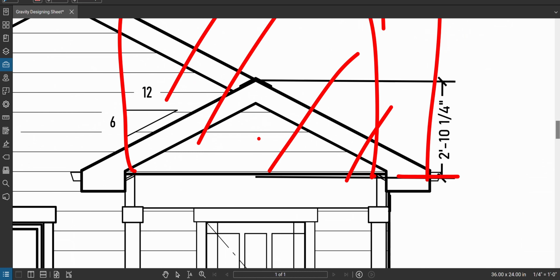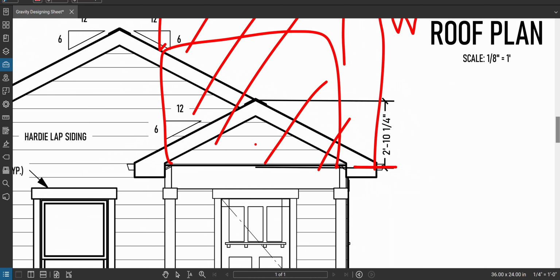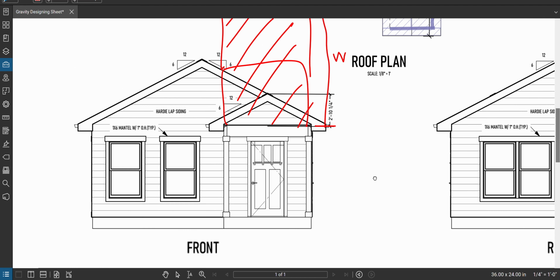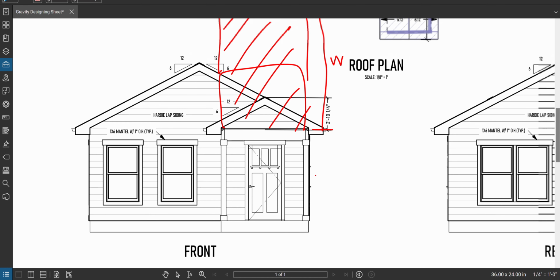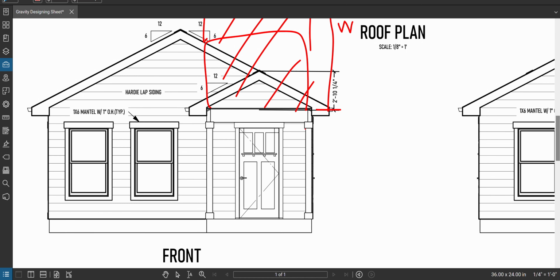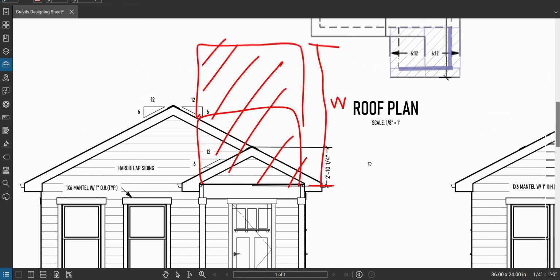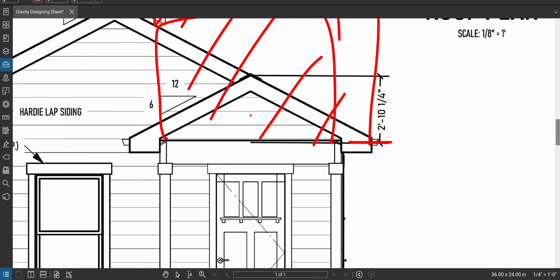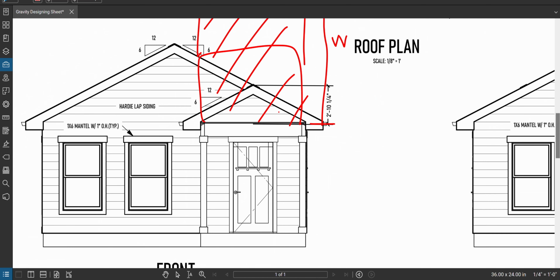Now, how much does this wall weigh? I believe the number for a wall assembly like this is 6 or 7 pounds per square foot. We're going to go with 8 pounds per square foot. Should be a little conservative here. But these numbers are just kind of previously established. They're in tables and charts and things that I can share just from other books and things. But you could do the math and figure these things out if you knew densities and things if you really wanted to. But we're just going to go with 8 pounds per square foot.